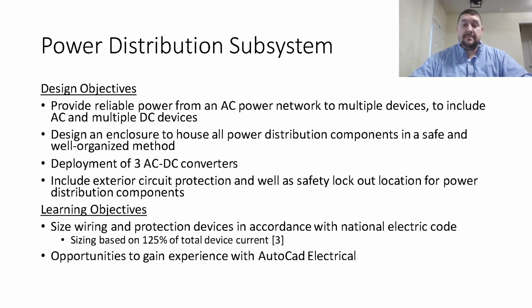But the main thing is you would take the total current of a device, its full rated current that you can see, and then you raise it by 25%, and then you set your protection or your wire size based on that number. So that allows you some wiggle room to be able to safely protect your device and your equipment, but also not have it continuously going offline.